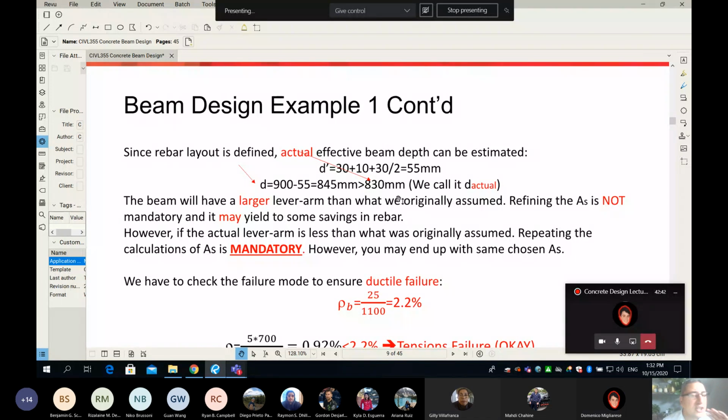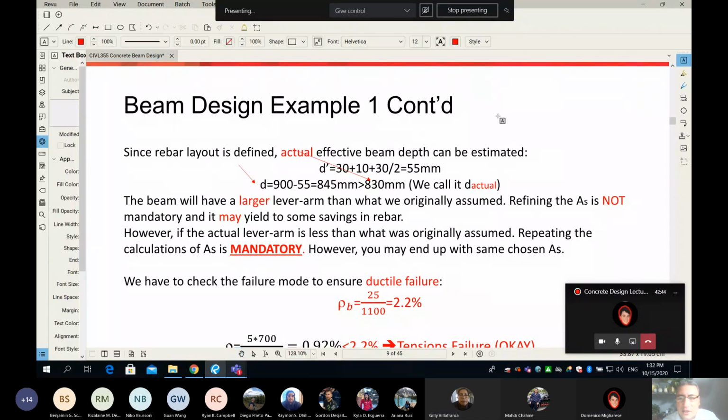3062. Okay, so I'm going to write it here, guys, because that's really a good example. 3062. Now, if I still use 30M rebar, what do you think? Nothing is going to change. 4 bars of 700 is 2800, so I cannot use 4 30M bars, because you will be below the 3062.